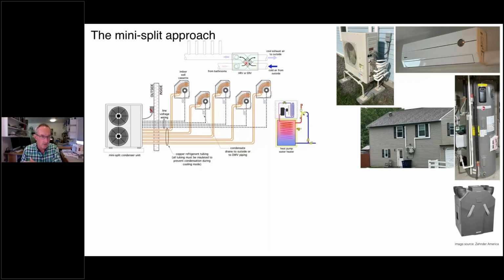An outgoing airstream, let's say in the winter, is on a relative basis warmer air, interior air that goes through the core of the heat exchanger. And then you have colder outside air coming in, absorbing some of that heat from the outgoing stream. And that becomes the preheated fresh air stream that then has to be distributed through the building through some kind of a ducting system. And there are different approaches.